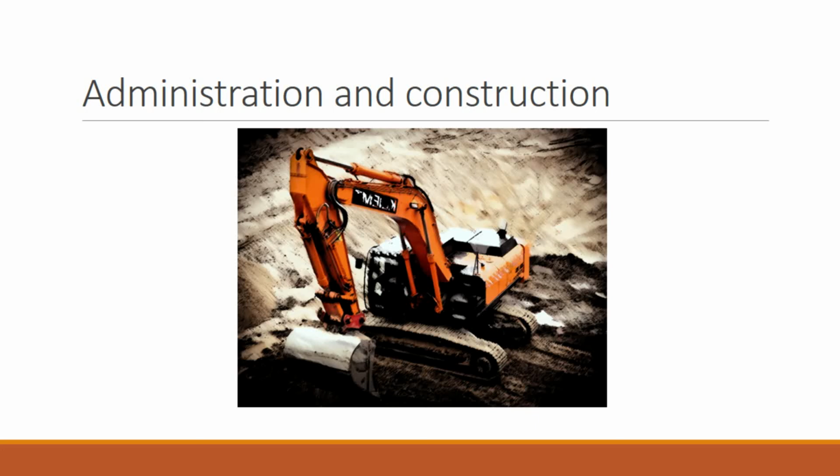Continue to involve the A&E, which is the architects and engineers, in meetings during construction. Additionally, the A&E should support construction administration by certifying shop drawings and submittals, issuing change bulletins, and, as necessary, analyzing payment and change order requests from the contractor. Be wary of the contractor making substitutions, since the quality can suffer greatly.